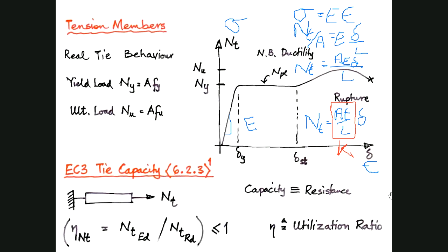When we have stress equals Young's modulus times strain, the material stiffness is Young's modulus, which describes the linear relationship between stress and strain, and that works up to the yield point. We can also turn that into the equivalent of load against displacement. In this graph, the slope is actually AE over L, because we're plotting load against displacement. So load is stiffness times displacement, and the stiffness value K is AE over L. If we double the cross-sectional area, we double the stiffness.